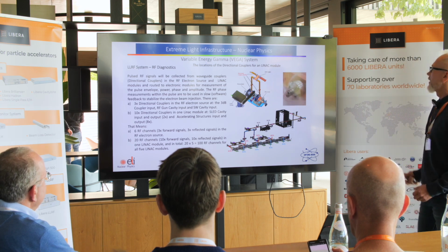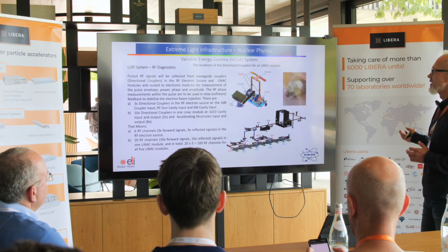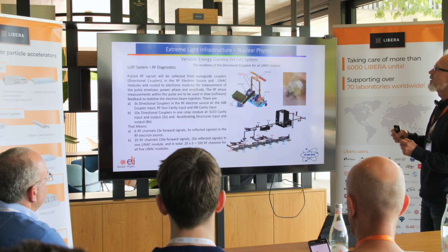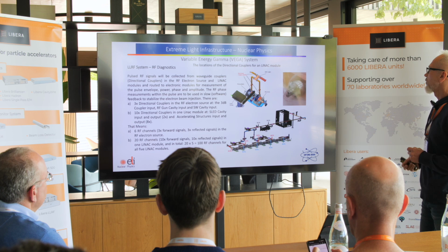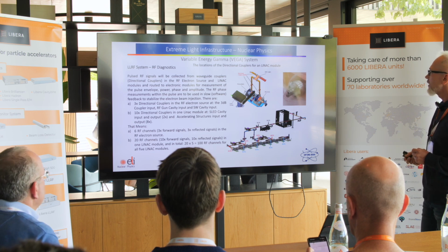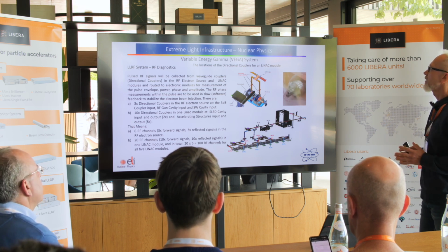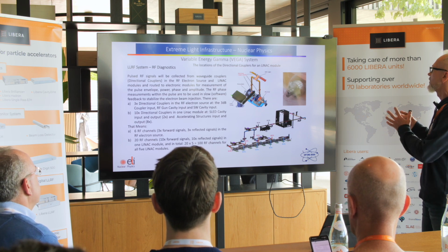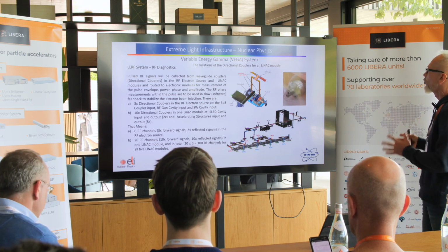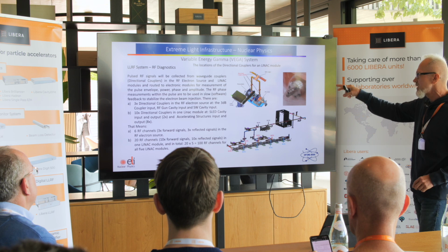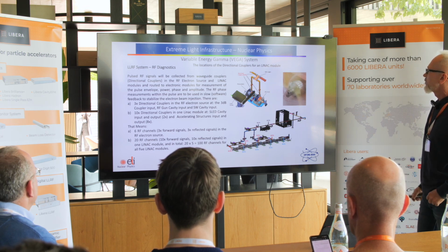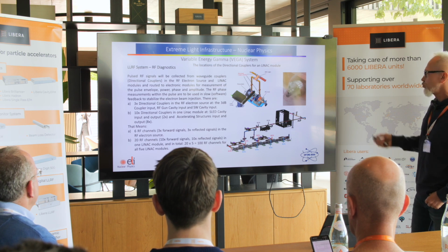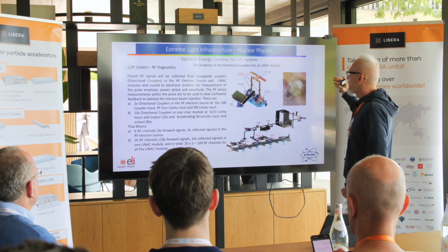So we analyze forward and reverse signals in order to adjust the generation of the low-level RF signal in order to be in phase and amplitude and in power in each module together with the laser which is generating the RF electron beam.